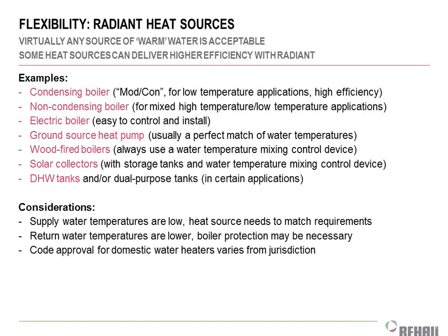You can use your geothermal system. A lot of you have probably heard of water-to-air geo systems. There are also water-to-water geo heat pumps. So you still have the same kind of field loop buried in the soccer field at the school or in your backyard at your house. And when the pipes come inside, instead of going to a water-to-air heat pump, they go to water-to-water.